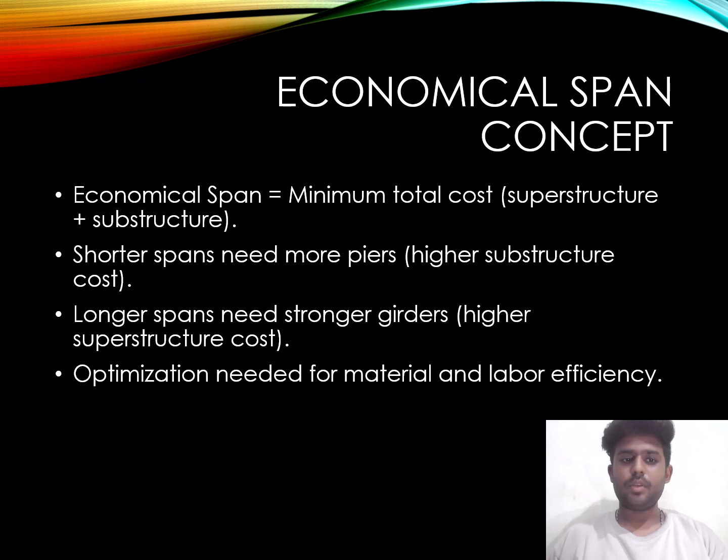Economical span concept. Economical span is the one with minimum total cost, here superstructure plus substructure. Next, a shorter span needs more piers, higher substructure cost. A longer span needs stronger girders, higher superstructure cost. And next, optimizing need for material and labor efficiency.